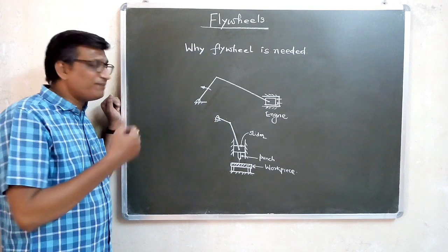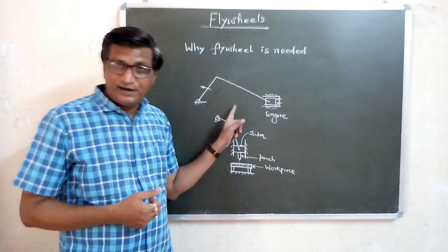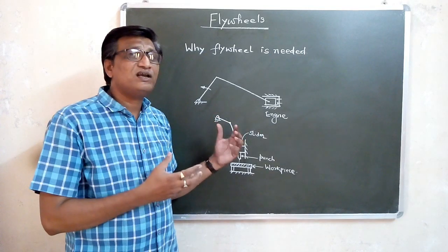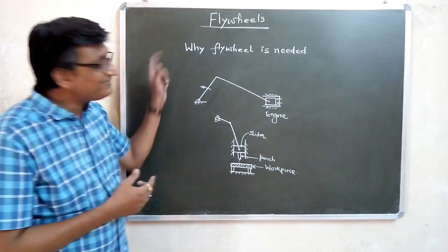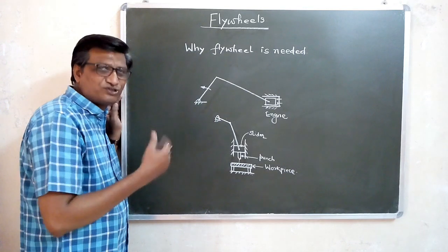Now how can it be done? In such cases, flywheels are employed. The flywheel will store the excess energy given during the power stroke and supply that energy during the suction stroke, compression stroke and exhaust stroke.